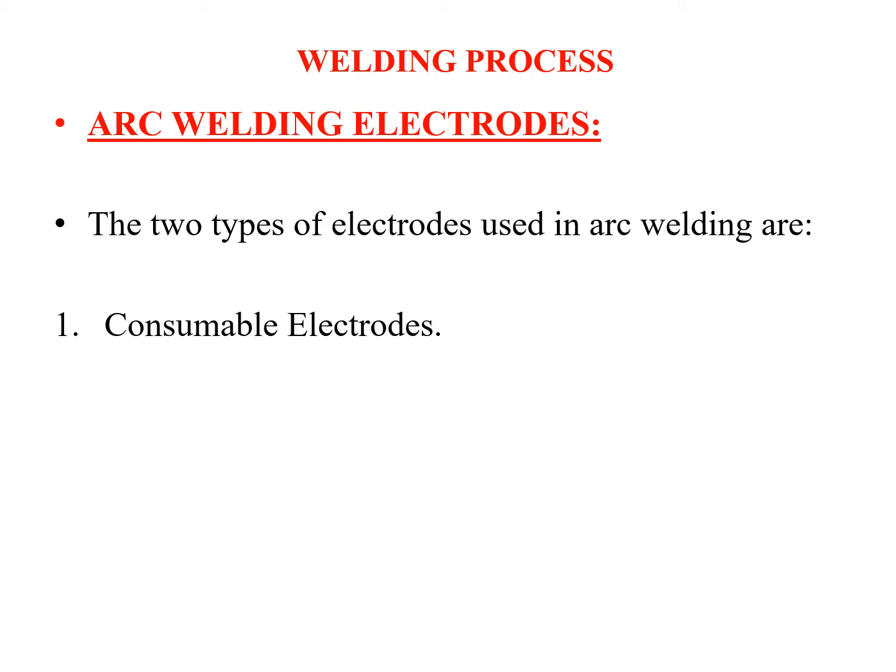Hence the coated consumable electrodes protect against rapid cooling by forming slag. This slag is chipped off later, after the weld has cooled down.